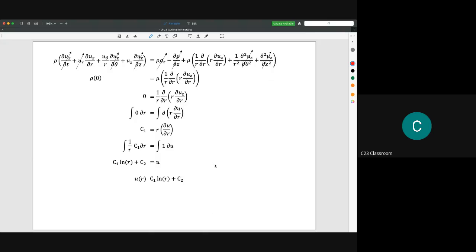They will have pressure, they will have gravity, and so on and so forth. Normally people will take the flow as a steady flow. Steady flow means there are no changes along time, so everything with d/dt will equal 0. That's why we take du_z/dt equal to 0.